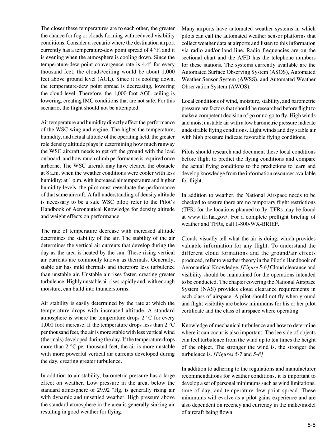Knowledge of mechanical turbulence and how to determine where it can occur is also important. The lee side of objects can feel turbulence from the wind up to 10 times the height of the object. The stronger the wind is, the stronger the turbulence is.